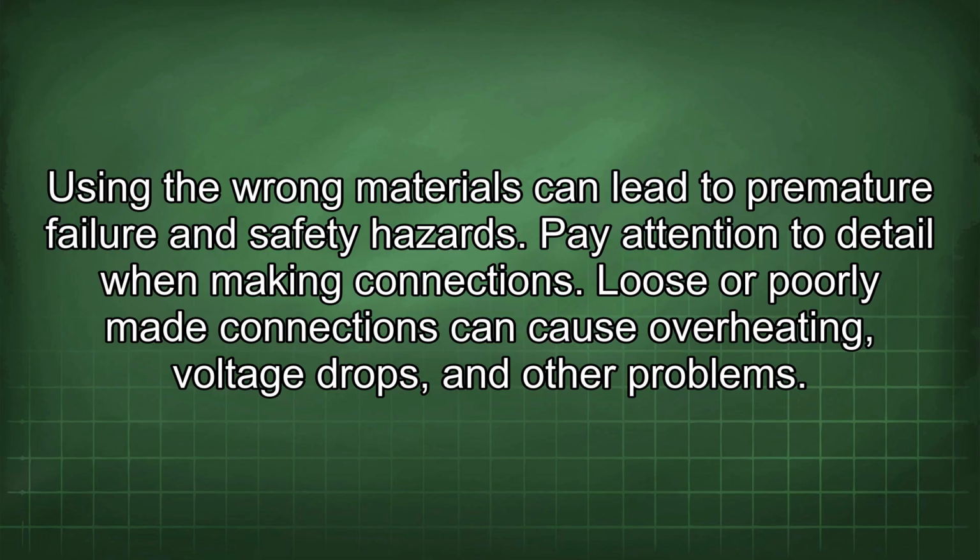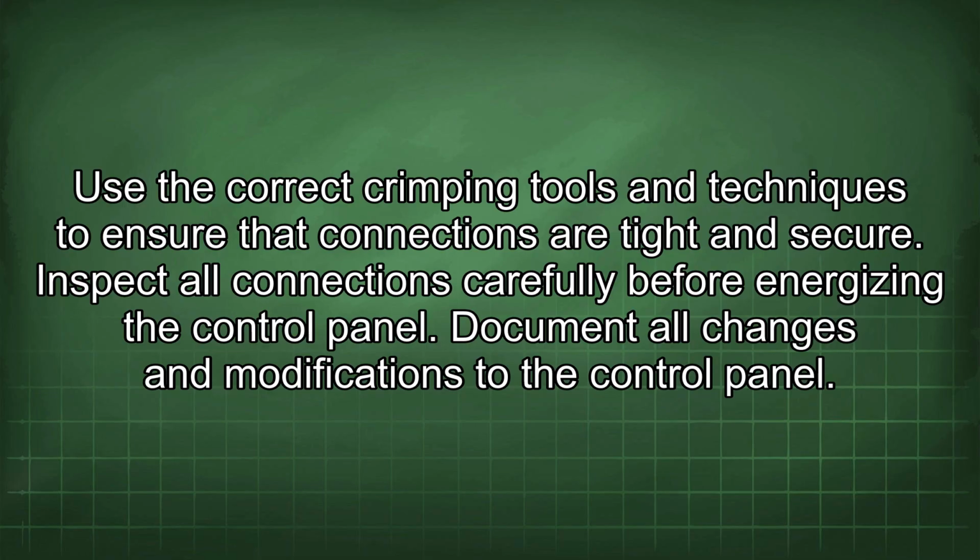Pay attention to detail when making connections. Loose or poorly made connections can cause overheating, voltage drops, and other problems. Use the correct crimping tools and techniques to ensure that connections are tight and secure. Inspect all connections carefully before energizing the control panel.